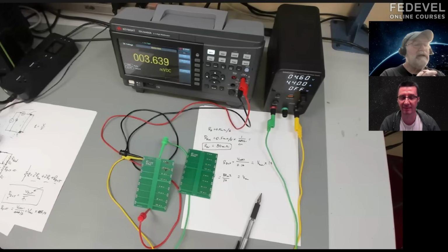When you look at a network processor, a high-end processor, a lot of the Intel, AMD processors in PCs these days, some of them are 100 watts. They're not a lot of voltage, maybe a volt of core voltage, but 100 watts. A volt supply consuming 100 watts, that's 100 amps. That's a lot of current. You're not going to put 100 amps through a 20 mil wide line. And that is the compelling case for why you want to use power planes. So using power planes, you can distribute the 100 amps. But the point you raise is, well, wait a minute.